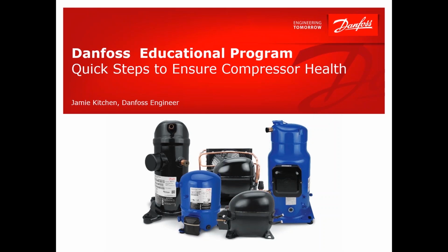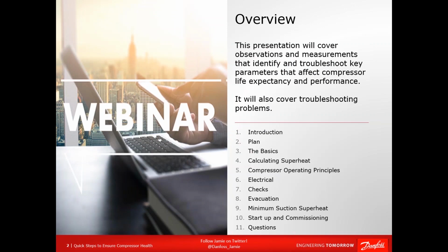All right, so as Michael said, we're going to focus today on compressors. Now, when you focus on compressor health, making sure the compressors run correctly, they're not making strange noises or drawing too much power, really most of your focus is actually not going to be on the compressor itself. Most of that focus is going to be on other parts of the system. The reason being is that all these other parts affect the compressor itself. So whether it is the refrigerant charge, the voltage that comes to it, whatever it happens to be, these all have an effect on the compressor.